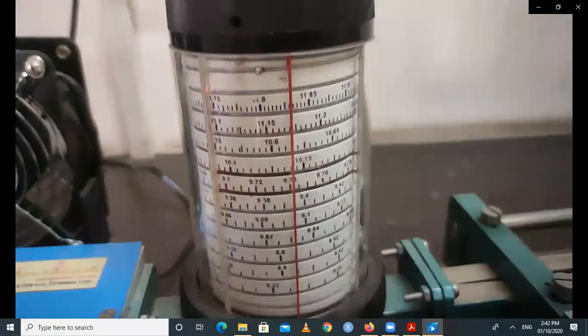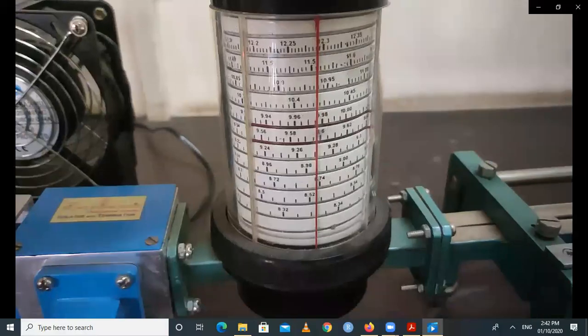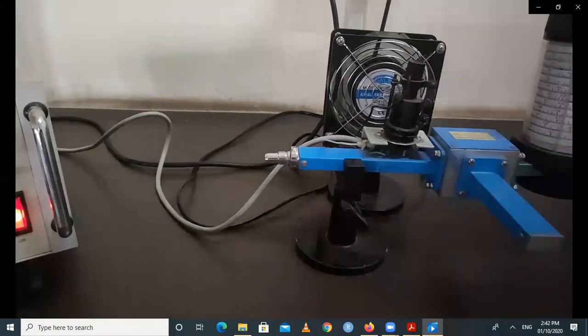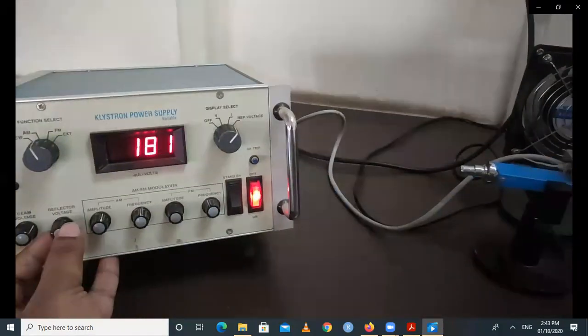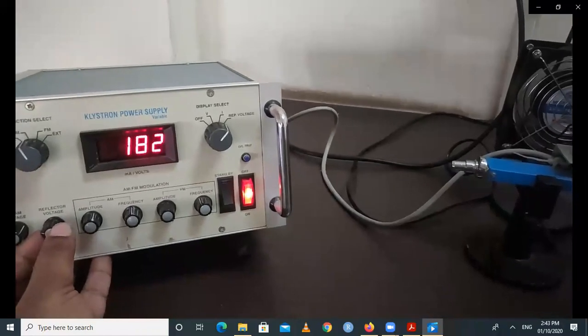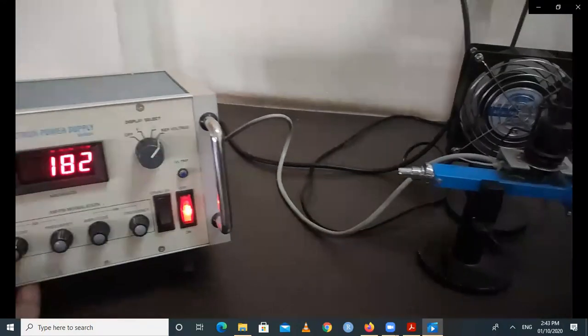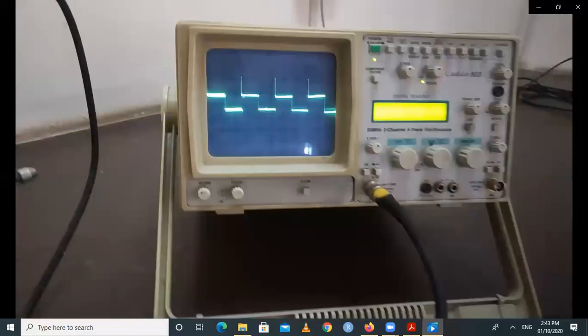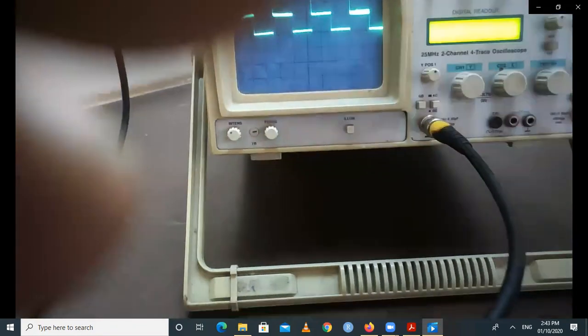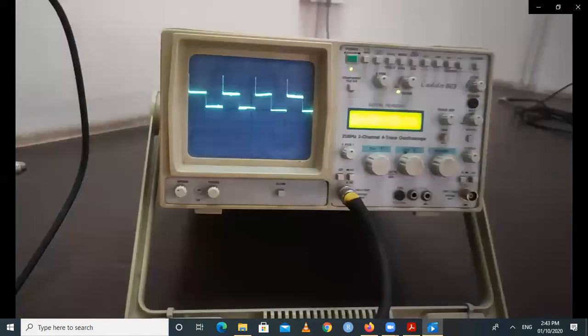And after that again you have to deselect that frequency meter, and again you have to take the third reading for this same mode by reducing this repeller voltage again. At this particular value, say it should be 182, you are getting a reduced output, so you have to again match, say it should be 1.4 multiplied by 0.2 volt.